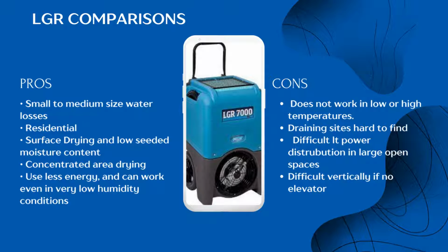If you have to have a concentrated area of drying, such as an office, doctor's office, maybe in some different rooms, even if you're running some other type of dehumidifier, they may be the tool of choice. They use less energy and can work in very low humidity conditions. However, as I've already said a couple of times, you cannot use them in low temperature or high heat. They have to stay within that range.